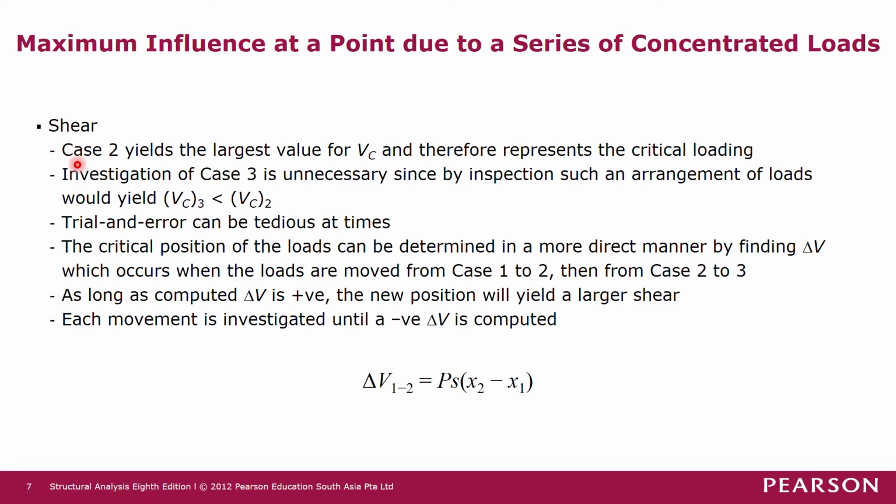So we can conclude that case 2 uses the largest value for VC and therefore represents the critical loading. Investigation of case 3 is unnecessary since, by inspection, such an arrangement of loads would yield VC3 smaller than VC2. Trial and error can be tedious at times.